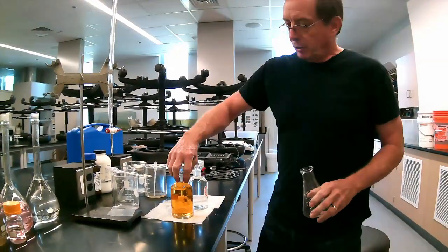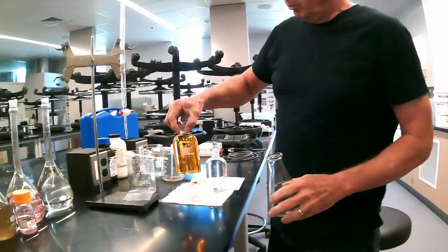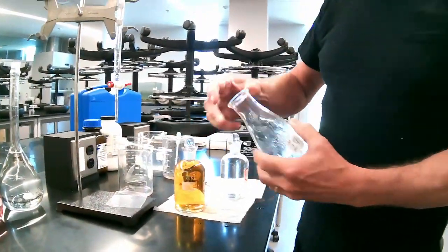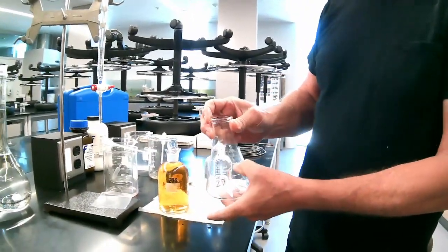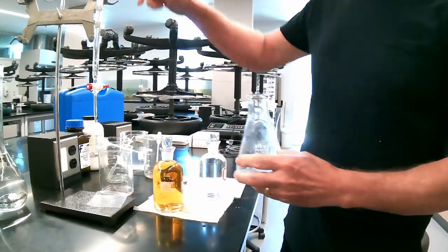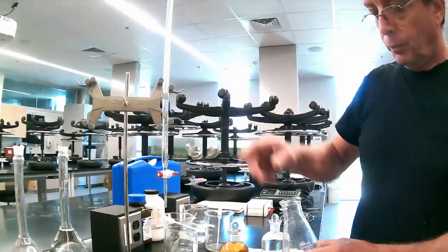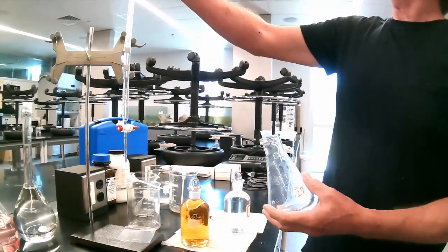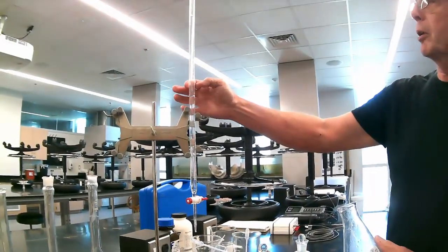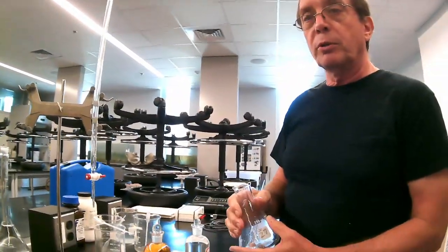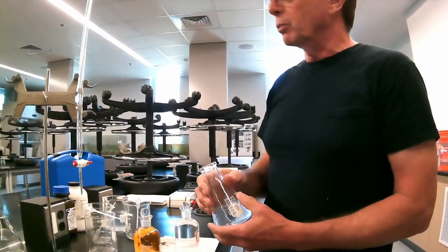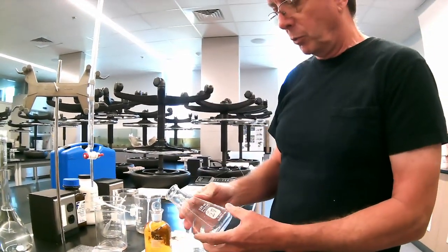Okay, so the BOD bottles hold exactly 300 milliliters. We are going to titrate a 200 milliliter sample of this using sodium thiosulfate. And the difference between where we start and where we end up is directly proportional to the milligrams of oxygen. So we can read it right off the burette when we're done.